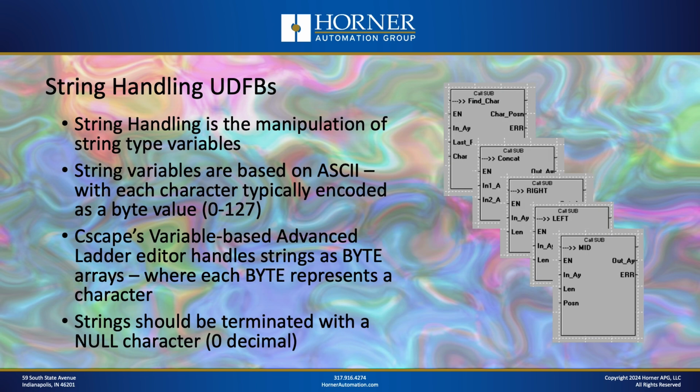All right, next we have string handling UDFBs. Now, ladder logic is not the greatest language for dealing with strings. Structured text, as an example, is much better. However, there's plenty of programmers that just prefer ladder. So what we've done is we've added a bunch of UDFBs that replicate some of the string functions that are available in structured text.